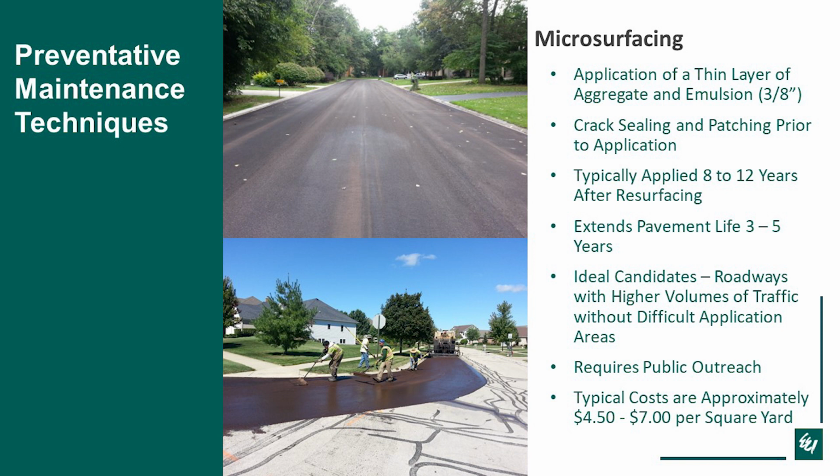it's ideal for roadways that have higher volumes of traffic without difficult application areas. So areas where the road is real curvy, there is a little bit of equipment train here, so it does have difficulty getting to those tight corners, even though you can still do it by hand. It's important to know that if you do it by hand, the surface doesn't come out the same as if it's placed mechanically, so there will be a little difference in color and whatnot.